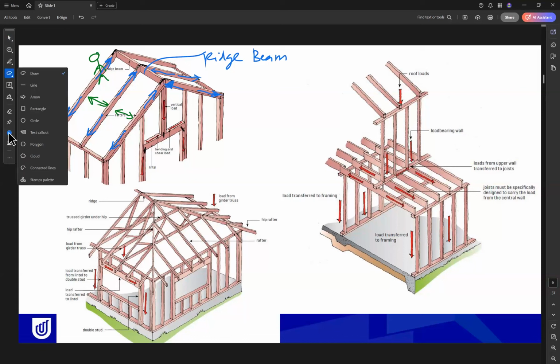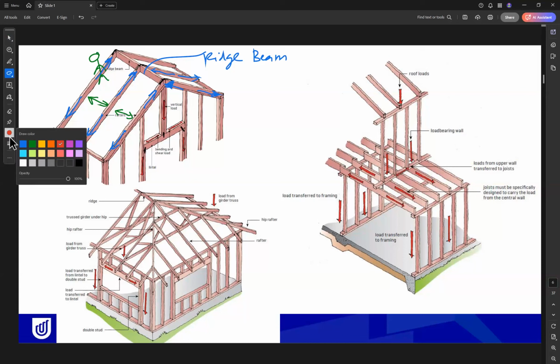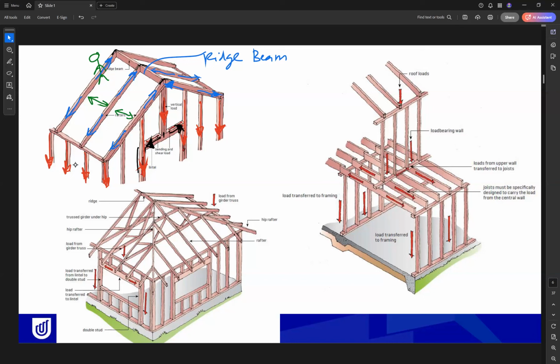Then, as you can see here, this beam will transfer the load to this column, and this column will take the load down. This ridge beam will transfer its load to this column here, and this column here, and this column here. Then, for example, if we want to make a door or something, we have added this beam. So the load of this column will be transferred through this beam in this direction and this beam in this direction, and then go back to the column.